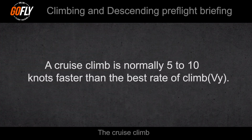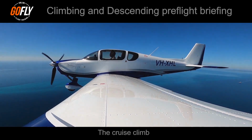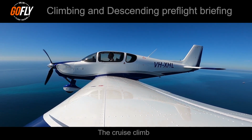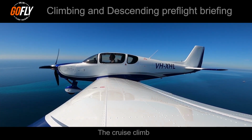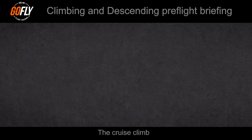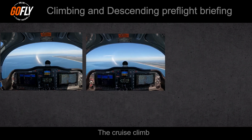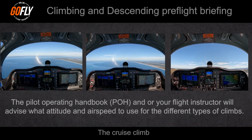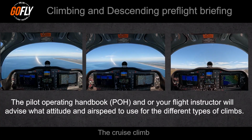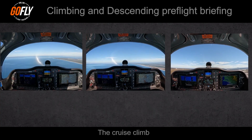A normal cruise climb is normally 5 to 10 knots faster than the best rate of climb, or Vy. The POH, or your flight instructor, will let you know what the attitude and airspeed is for your particular aircraft for a normal cruise climb. The attitude will also look different between normal cruise, best rate, and best angle. Your flight instructor will advise what attitude and airspeed looks like for your aircraft type for that particular climb.